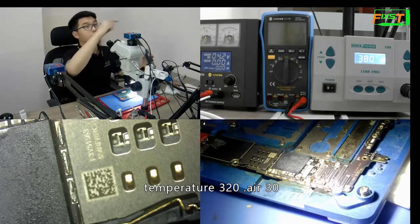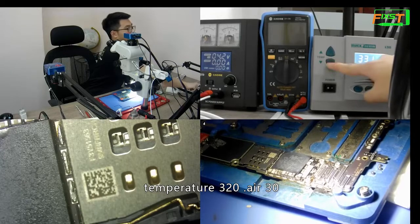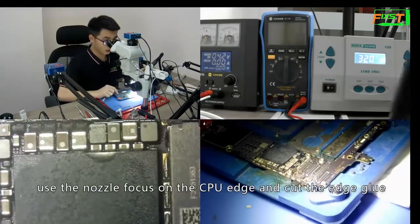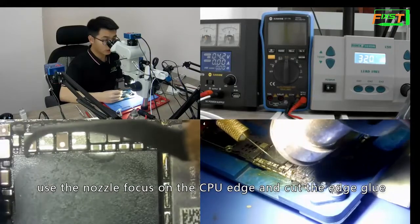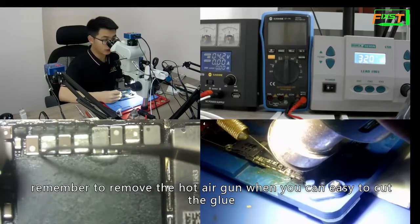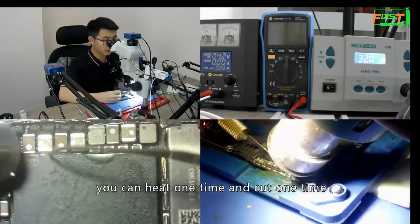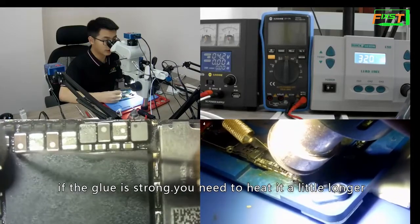Temperature 320, air 30. Use the nozzle, focus on the CPU edge and cut the edge glue. Remember to remove the hot air gun so that it is easy to cut the glue. You can heat one time and cut one time. If the glue is strong, you need to heat it a little longer.